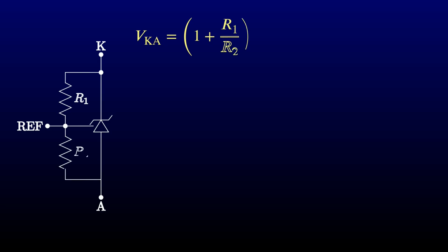These ICs generally use the same schematic symbol as the Zener diode, except that it has an extra terminal, the reference pin. The reference pin is used to program the Zener voltage. You program it by hooking it to a voltage divider between the anode and cathode pins. The apparent Zener voltage will be the reciprocal of the divider ratio times a reference voltage given in the device datasheet. Usually, the manufacturers make the reference voltage 1.25 or 2.5 volts. By choosing the divider resistors, a high voltage part like the TL431 can be set to a voltage anywhere from 2.5 to 36 volts.